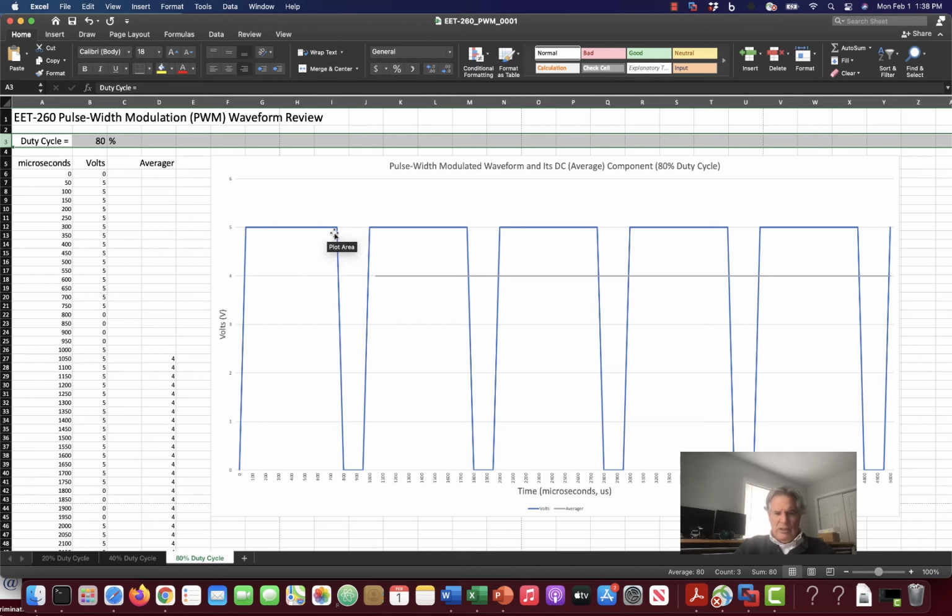You got this switching thing, and with some inductance and capacitance, you can make a low pass filter. And with 5 volts in, you could produce, say, 3.3 volts out, or 2.5 volts out, or 1.8 volts out. And so the switching technique, pulse width modulation, is at the heart of a lot of power supply designs. And as long as you use good quality components, you don't waste the power.